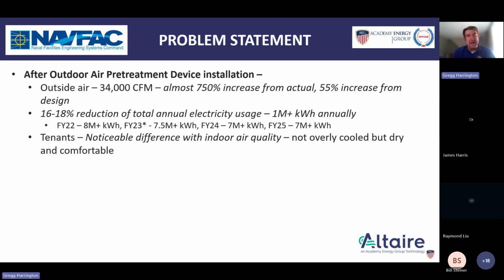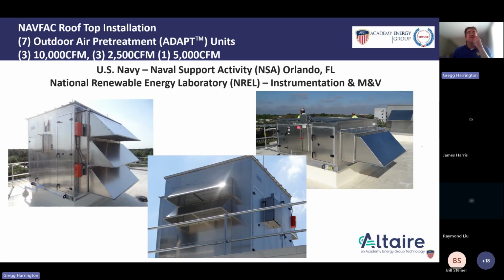So what does that actually look like? For us, in this case, 7 air handlers on the roof. We weren't in a position where we could easily put one DOAS unit to feed multiple air handlers. So the most effective strategy based on the demands that the zones had for each of these air handlers was to apply our pretreatment unit. And that pretreatment unit, based on the capacity within the air handler itself relative to static, we were able to just supply coil and filter units without the need to augment any fan.